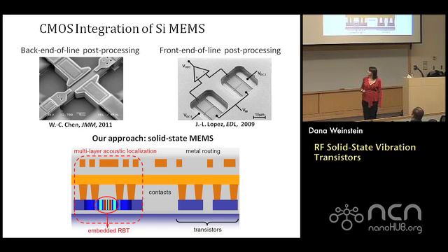What you see here is a cross-section of a hypothetical CMOS stack, in this case SOI, so we have a buried oxide layer underneath. And at the transistor level, we can pattern the silicon and pattern materials around the structure, say vias or metal layers, in order to confine acoustic vibrations in this solid medium. And we can have this side by side with transistors, right? Really at the front end process. So that was the vision here.